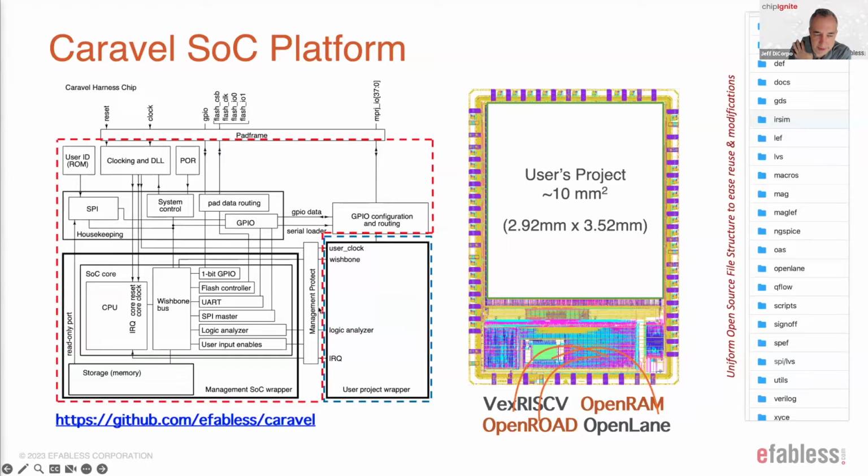It provides the ability to integrate. That SoC extends a number of interfaces out to this user project area that you can integrate with for your specific design if you need it or you choose to. It includes a Wishbone bus and a set of logic analyzer probes, as well as some interfaces to clock and IRQ and some other functions and reset as well.